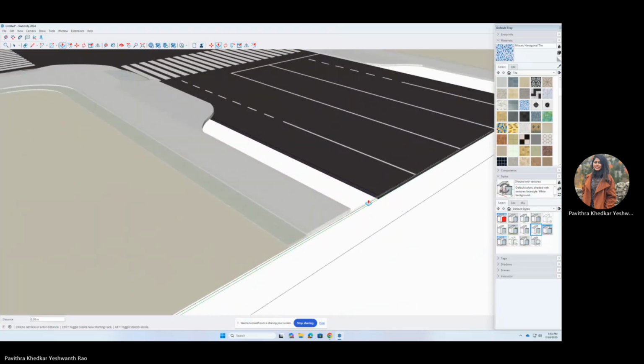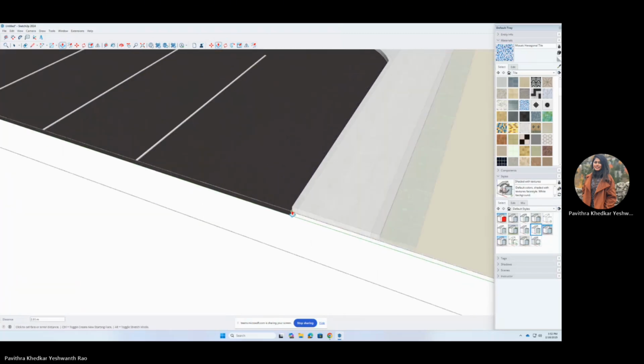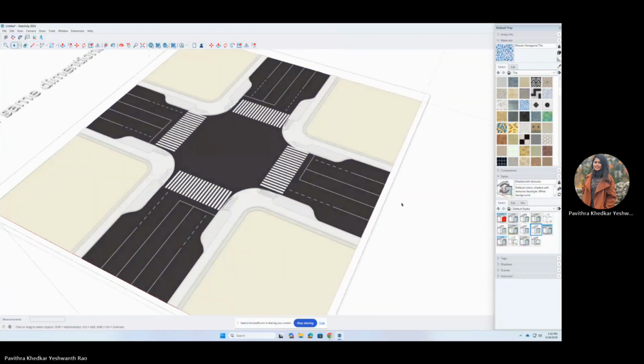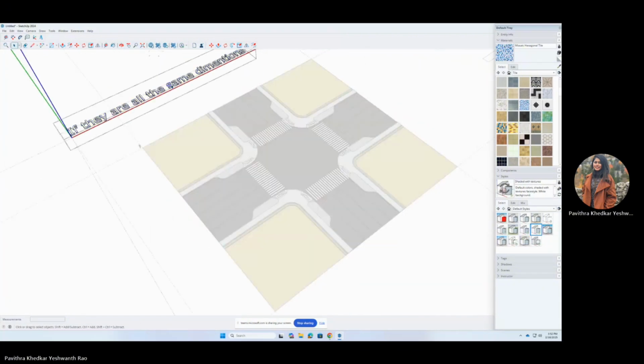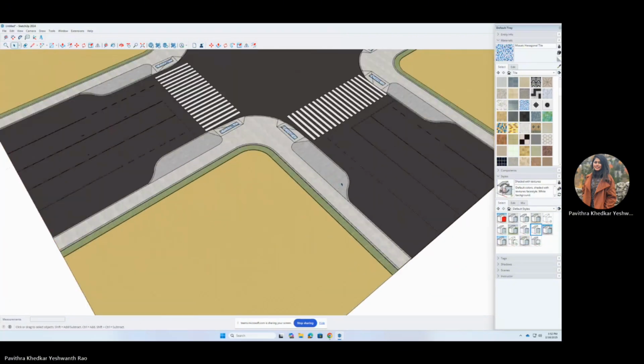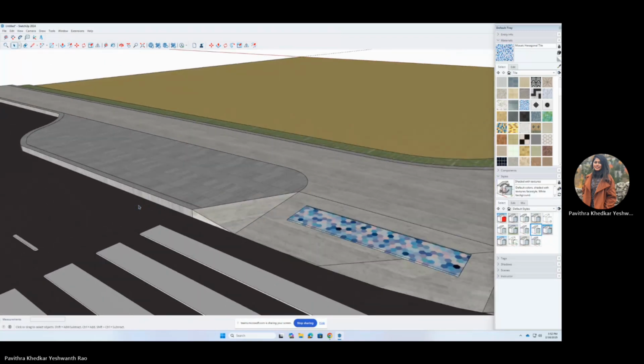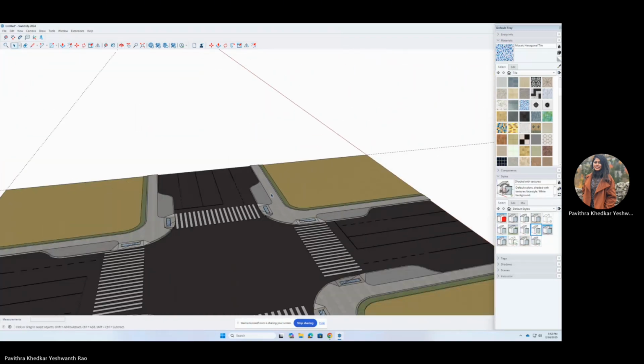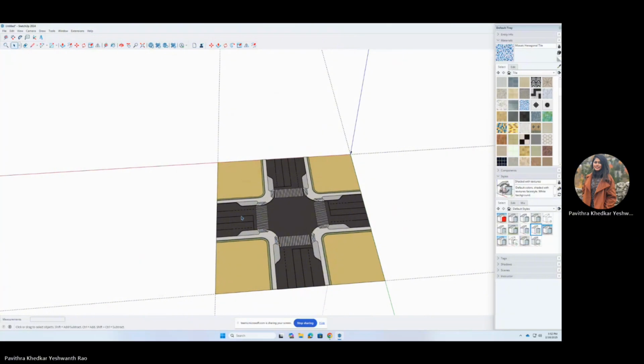Unhide geometry within a group. Enter the group or component, locate the hidden elements, and right-click and select Unhide. Verify all reference geometry is visible, check all of them if necessary, and restore properly.